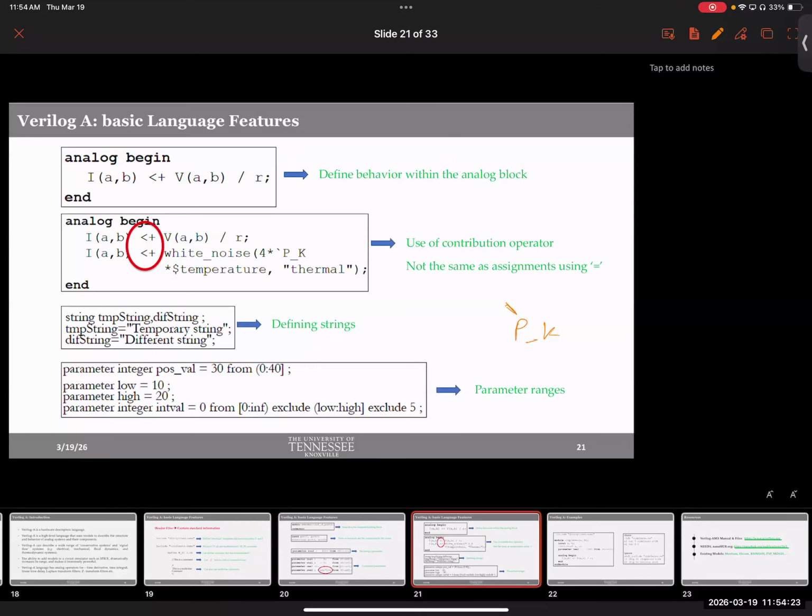Now, this is how you call temperature. See that? You can request the simulation temperature. And where does it come from? When you simulate in SPICE, most simulators will allow you to set the temperature for simulation. Okay? Does that make sense? You can simulate .temp something. You can always set the temperature for simulation. Whether or not that translates into something depends on the other models. There are some transistor models which handle temperature. There are some that don't.